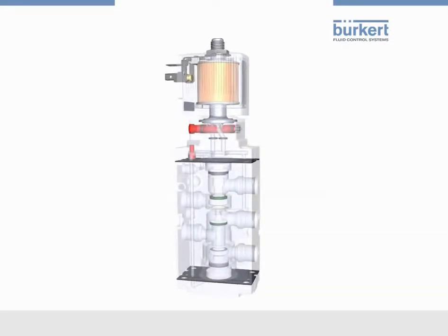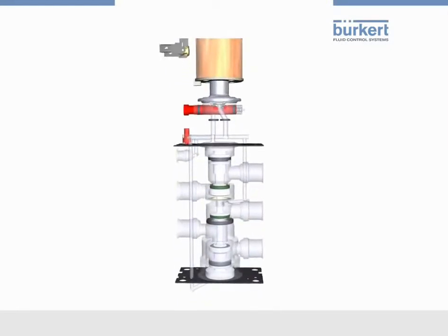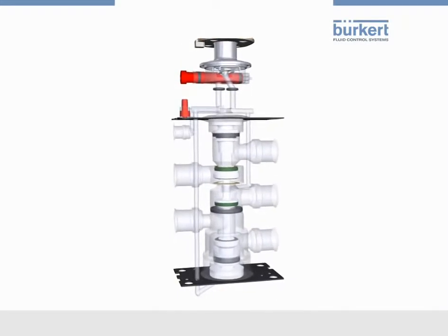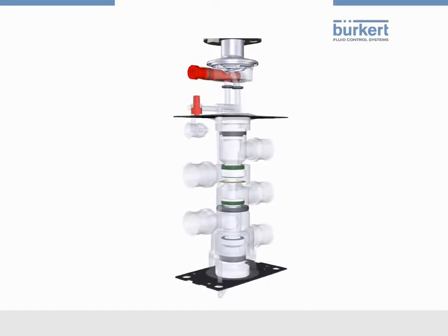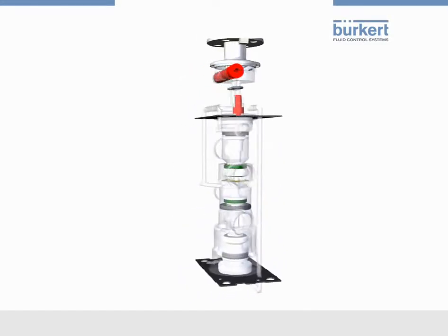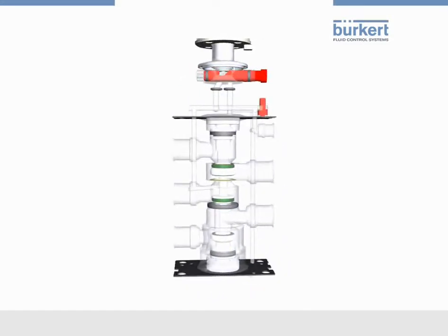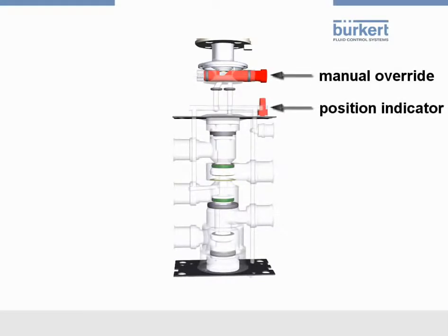In general, Type 6519 consists of a servo-assisted valve Type 6014 and the pneumatic amplifier. The housing consists of a piston, 2 diaphragms, various sealings, and 5 pneumatic connections. Moreover, we have a manual override and a position indicator.